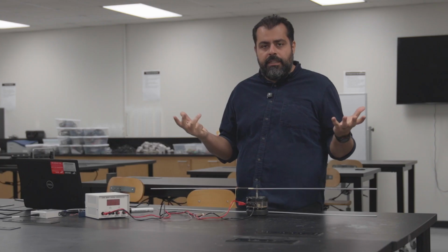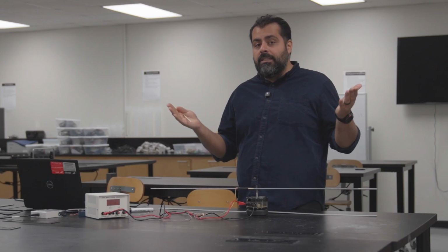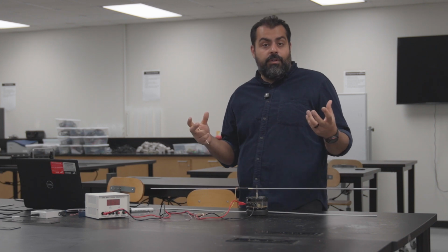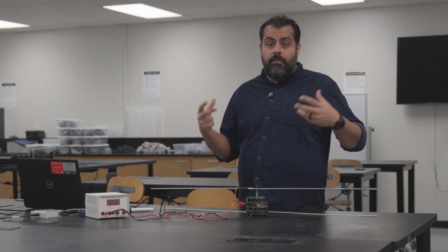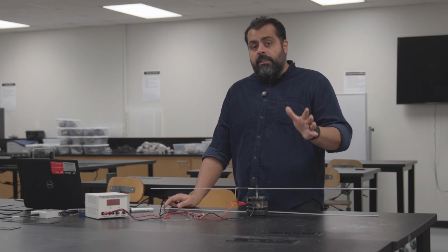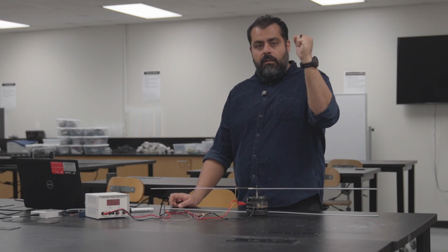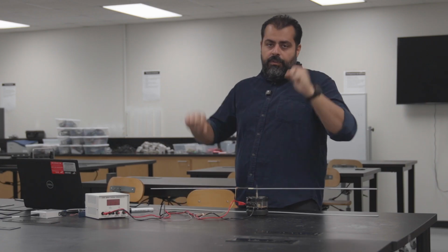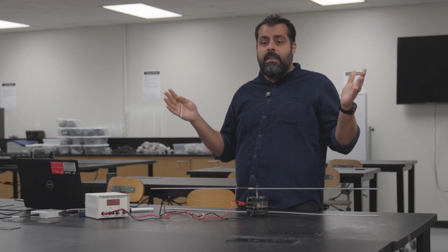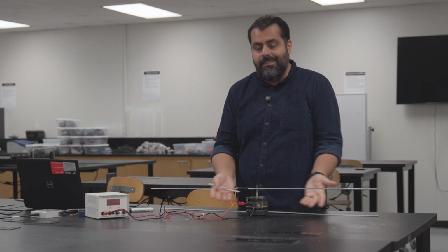Why do we have two different theories? The reason is that those theories are developed based on the general formula we have for the vibration of a beam that is given to you in the lecture slides, right? And those theories are developed for a cantilever beam. What is a cantilever beam? It has a fixed end, no movement at all, and a free end, freely moving. And the second theory is developed for the free beam, which essentially has no support whatsoever, just two free ends. This beam right here is none of them, right?